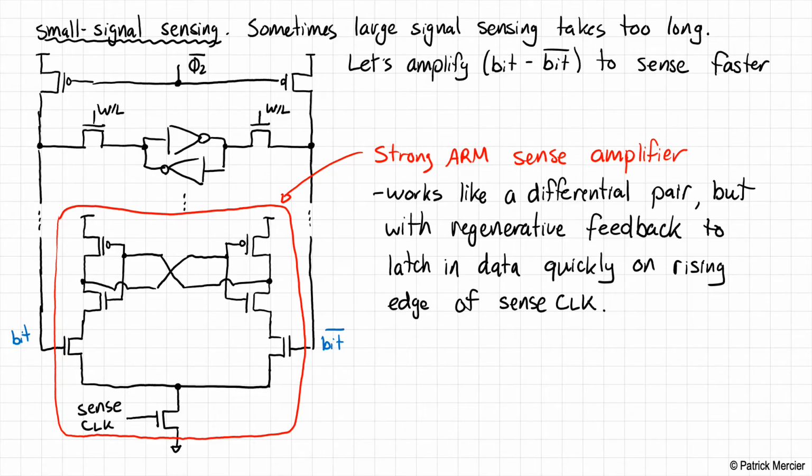Okay, and what this does is starts to cause current to flow through the differential amplifier, or the differential pair rather. So if current flows, say for example, more in the left side where bit is being activated because it's staying at logic 1, whereas bit bar is being discharged, and so there's a little less current flowing through the right NMOS differential transistor, then there's more current that's going to flow into the left inverter as opposed to the right inverter.